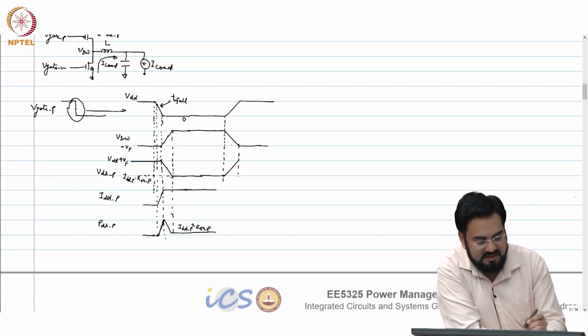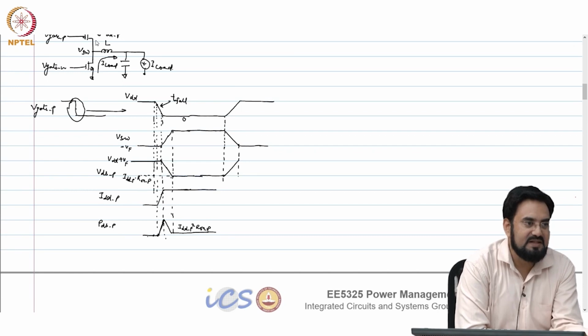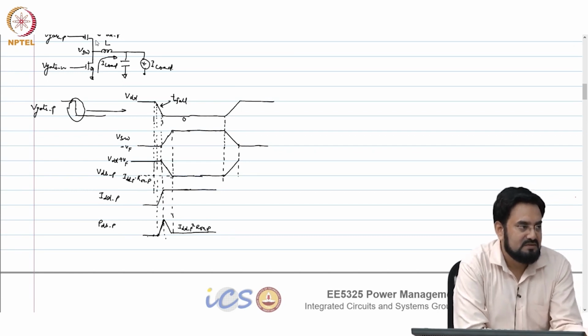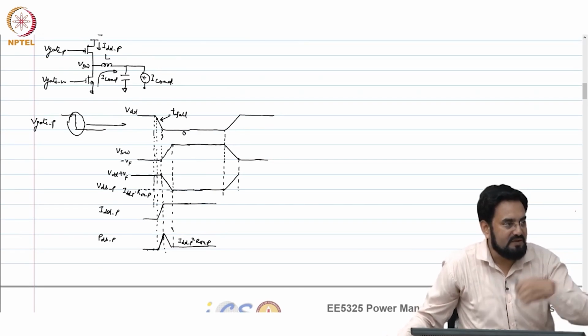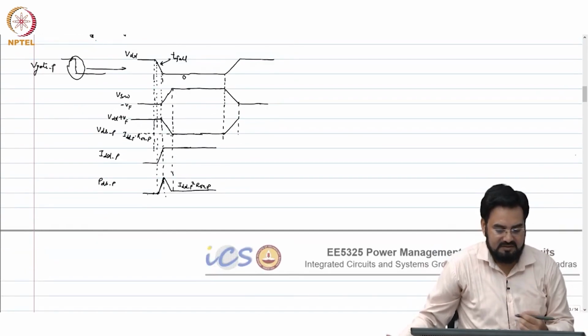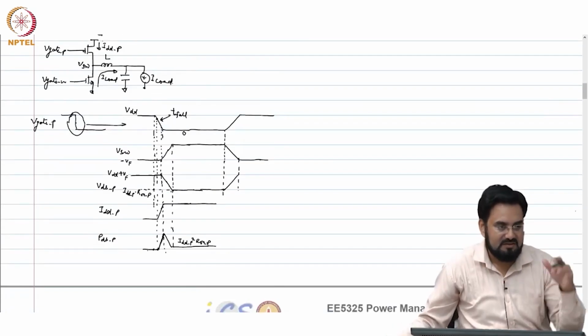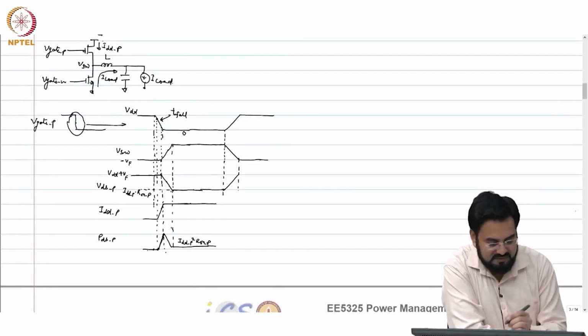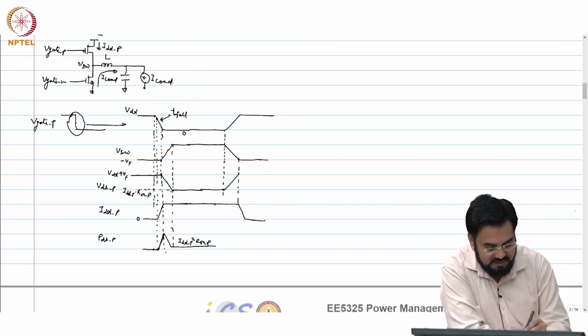And this will happen actually when this MOSFET completely turns off, correct. So, in order to have the current flowing through that FET, that body diode, it has to be very weak or almost near turn off. So, if your current starts dropping from here, this is the point where it goes to 0.